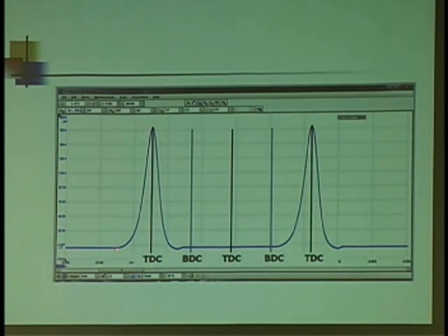But here's an interesting concept. Let's see, this works on, help me out here. Was it Boyle's law? About the gases and volumes and pressures? I'm not that smart. But it seems to me if I start off, the piston's at the bottom of its stroke, I've got all this volume of air now in the cylinder. The intake valve closed just after BDC, right? So now I've got a shut container, and I'm going to move the piston up. And as I change that volume, the pressure of that air is going to increase, right?